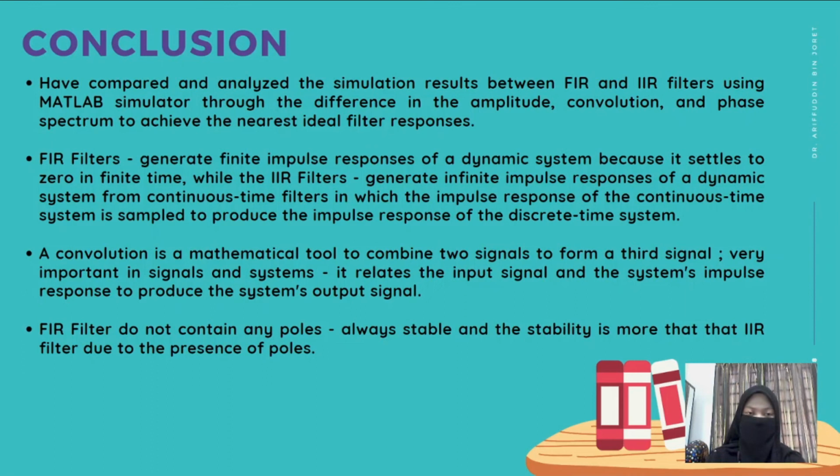In this project, we have compared and analyzed the simulation results between finite impulse response and infinite impulse response filters using the MATLAB simulator, through the differences in the amplitude, convolution, and phase spectrum, to achieve the nearest ideal filter response. Once the comparison is made, we can see that finite impulse response filters generate finite impulse responses of a dynamic system because it settles to zero in finite time, while infinite impulse response filters generate infinite impulse responses of a dynamic system from continuous time filters, in which the impulse response of the continuous time system is sampled to produce the impulse response of the discrete time system.